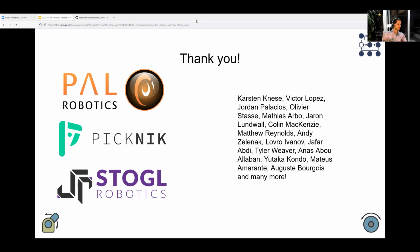We have another question from Rafael. He asked if he should use ROS2 control basically, or whether he can write his own controllers. You can write your own controllers. The question is of course what's there for you. If you need some forwarding and stuff like that, it will be simple. Where I think it makes sense to look at ROS control or ROS2 control is when you want to extend the system, so you want to add an additional sensor.